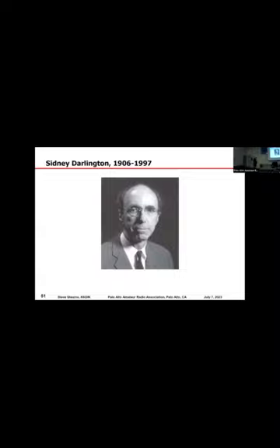Okay, but what's interesting is this lossless two-port, because he actually shows how to construct it. Darlington synthesis is all about how you construct the reactance two-port so that it gives you the desired impedance behavior. So it occurred to me, if I can construct two-ports, then formally I can invert those two-ports and come up with a mathematical inverse, so that when you connect two networks in cascade, they cancel each other out perfectly at all frequencies.